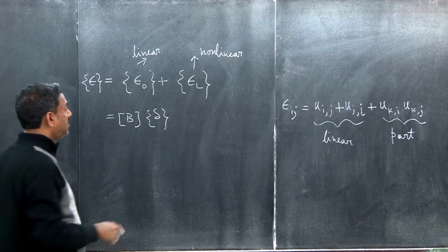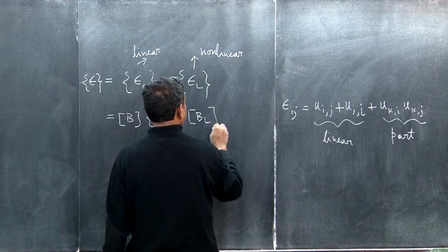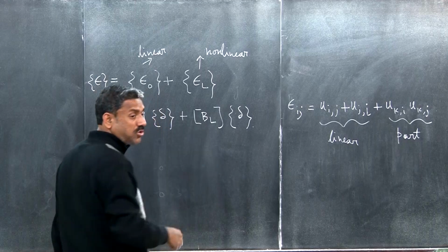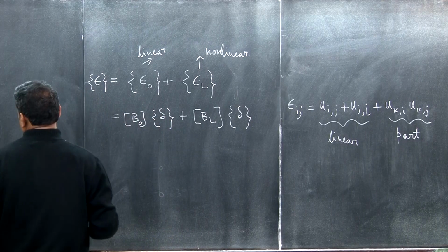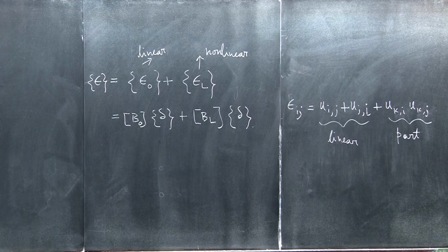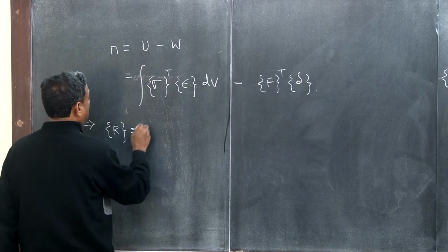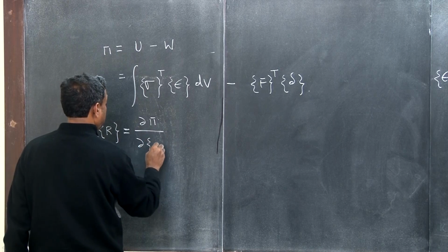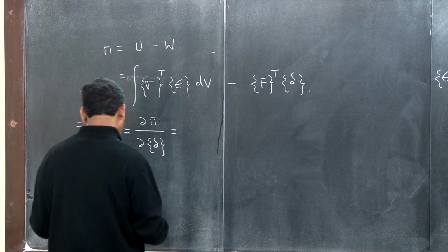Strain displacement matrix. Whether the non-linear term, if you see, you can also point out another non-linear one: BL is a non-linear one, okay, B0 and BL. So now, when you are coming back here, you want to find out R, the del pi by del delta, okay.